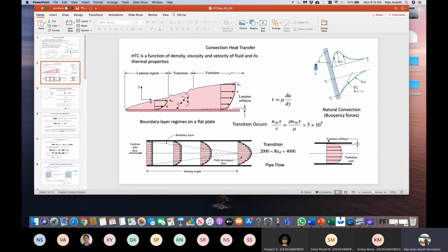This is a non-dimensional number. On a pipe, there is an entrance effect occurring, as I mentioned earlier. That slowly builds up the boundary layer on the surface until it meets here, fully developed flow. For laminar, this is a parabolic shape, and eventually it becomes turbulent. When it becomes turbulent, it becomes very sharp locally here. This is the turbulent core, they call it.